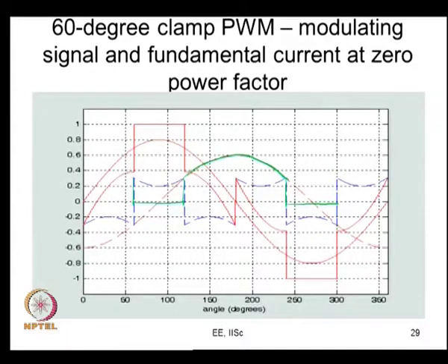So, you can see that the energy loss is quite high. You are not clamping the phase when the current through the phase, or the switching energy loss, is high. So, this is not the right thing to do. It will result in a very small reduction in your switching loss when you average it over a cycle.